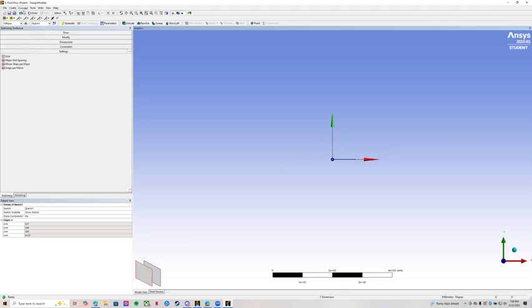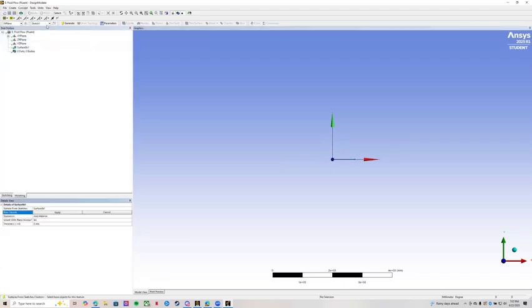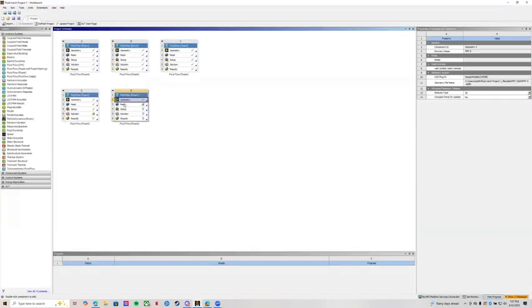Next thing you can do is go to concepts, surface from sketches, go up here, box select, select your sketch, apply the base objects, and generate, and it'll give you a surface from your sketch. So you can see it's gray. That means you got your surface. So now we're going to go ahead and click out of this. The geometry is already done.